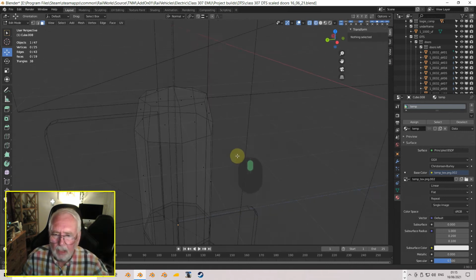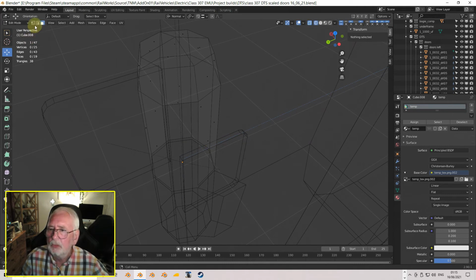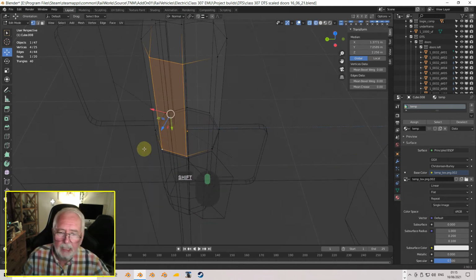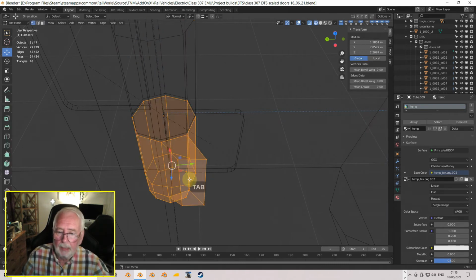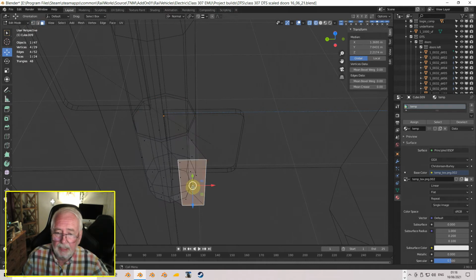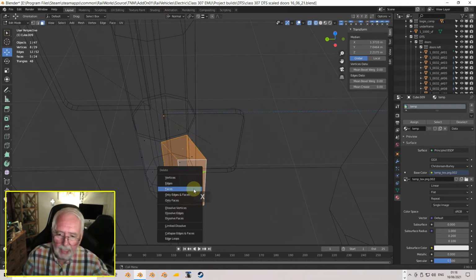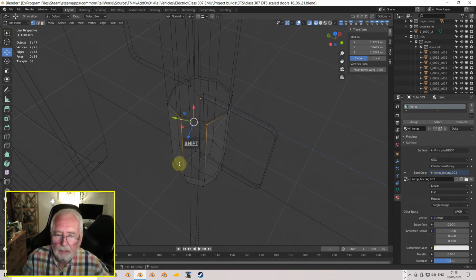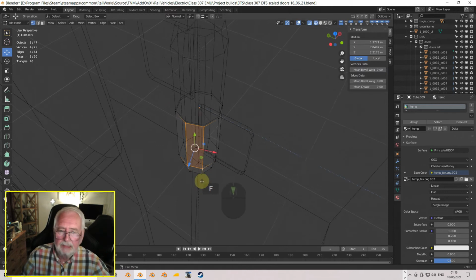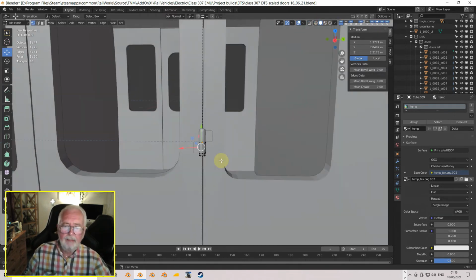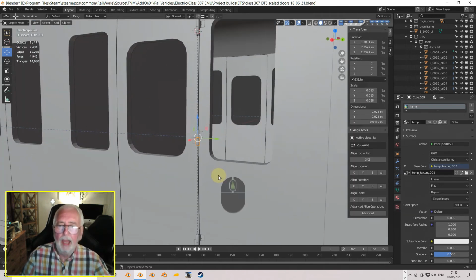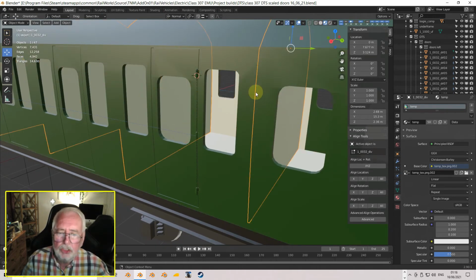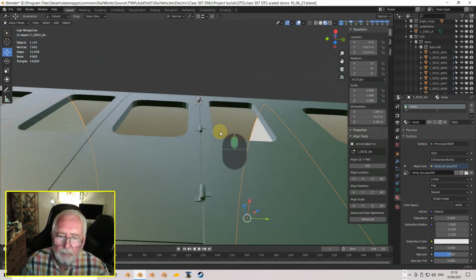Okay, just need to go in and repair. If you're not going to see it, you don't have to create the face, it all saves on the amount of geometry. Okay, there we go, and F. Okay, same thing with the bottom one there. Face mode, select that face and increase the selection, X, and delete faces, and repair this face. There we go. And so now go back here, there are our hinges. Okay, and that's it. There is our hinge, or our hinges. Okay, so yeah, happy with that.